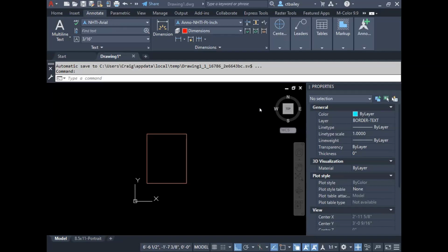When you do the added stretch, you need to slice through, in this case, two vertical members. Oh, we only had to slice through one vertical. So when you grab your frame, it only stretched one of the verticals. So what I'd like you to do is pick the stretch action. Left click, right click. Action select is new select. We're not modifying it, we're wiping it out. We're gonna use that first corner.